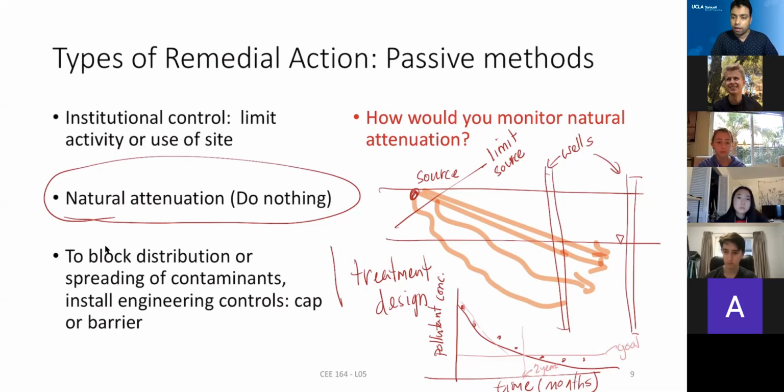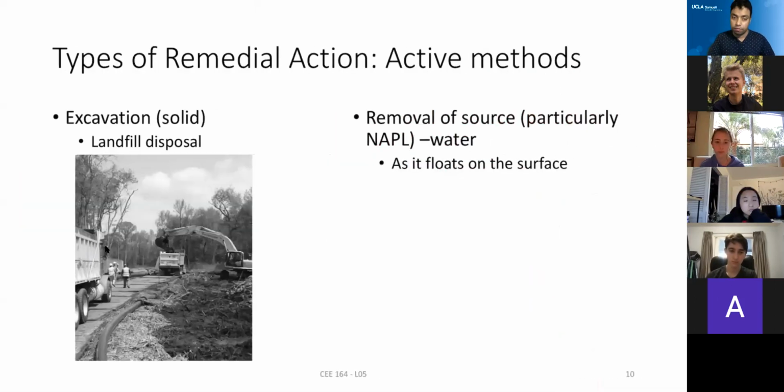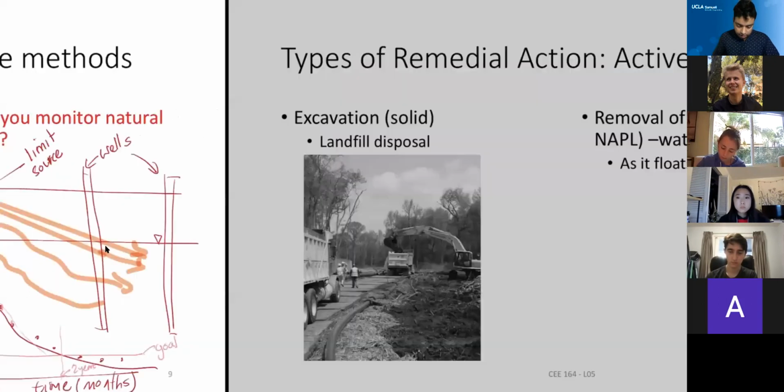And the challenge here is where to place that well. How do you know where the location should be? Obviously that's based on the initial monitoring data. You take different random locations and measure the concentrations. Based on that, you create a map, and then based on that map, you strategically put the locations, and then you pump all the water if you want to capture it. So what we are going to learn in the next couple of slides is how to calculate that capture zone.